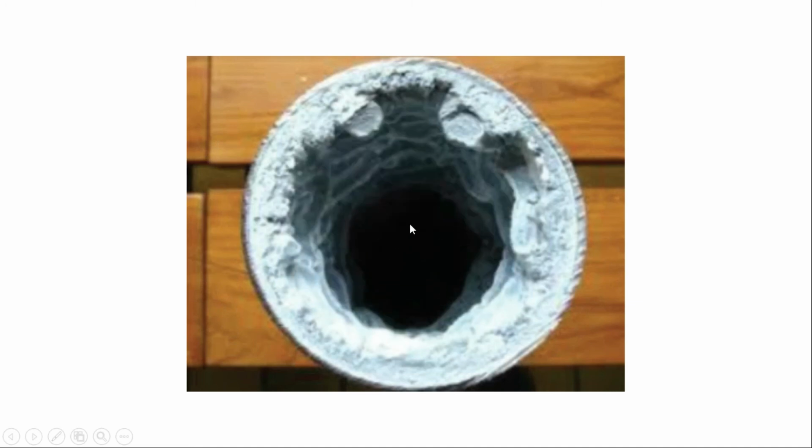So this is a diagram which shows a circular pipe which has fouling at the inner surfaces. As you can see, there is a thick layer of deposits at the inner surface of the tube. So ultimately it will reduce the flow area and it will increase the resistance to the heat transfer rate. So the fouling should be minimized in the heat transfer equipment.